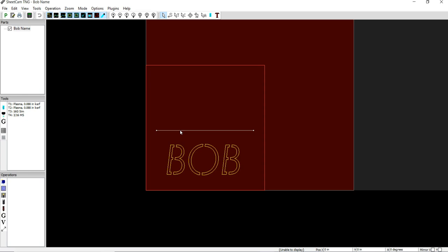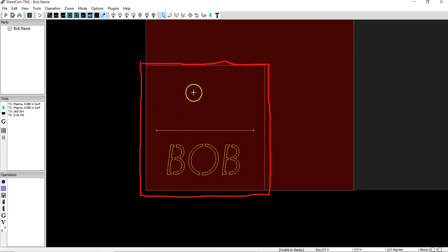And like many of you who have potentially cut wood or 2x4s, we know that we can cut on the outside of this, and it will be preserving the integrity and the scaling of this shape, as opposed to cutting on the inside of this, if I could draw, and it preserves the integrity of the outside shape. So whichever side of the wood, or in this case the metal that you're saving, you always want to make sure that the blade width is put on the outside of it.